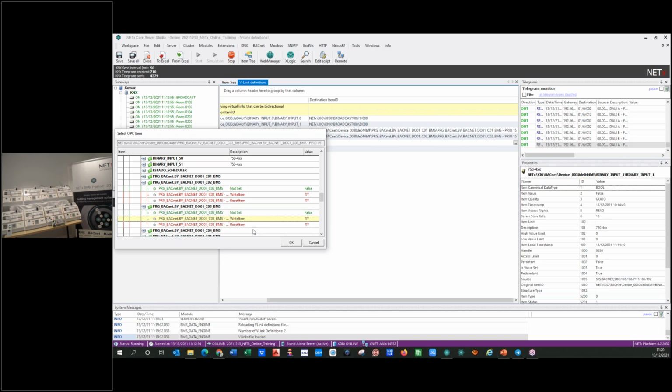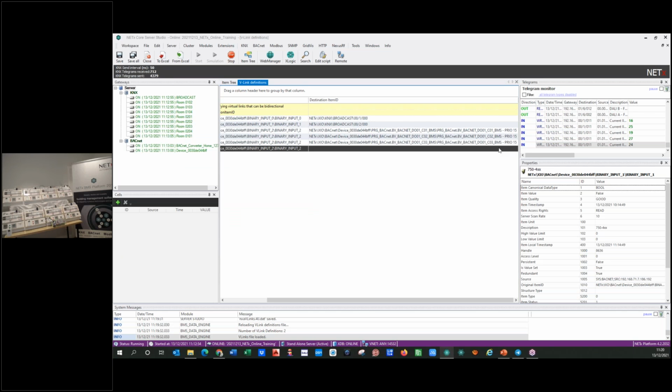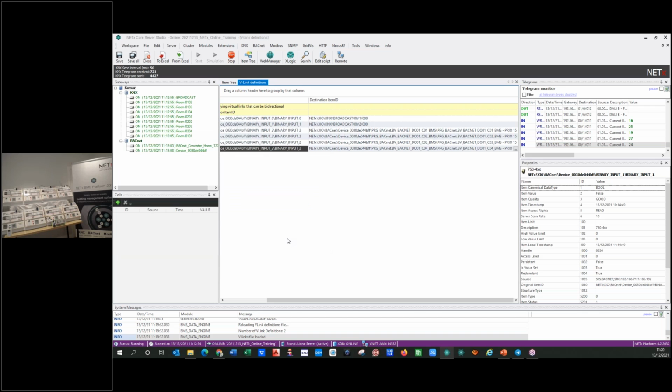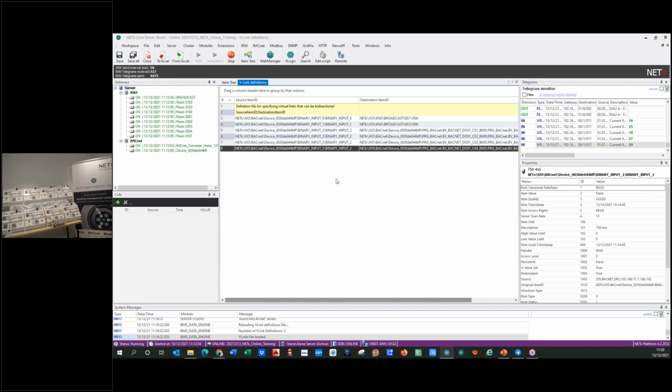It's like a scene, a sort of scene, very easily done. If something changes with that input, you will have 4 lights, 4 outputs in BACnet activated with the input number 2, this is the third one. The first and the second are affecting KNX lights and shutters.